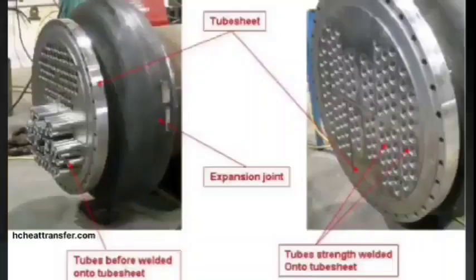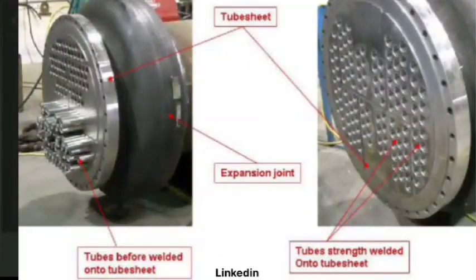And this strength comes into the picture when it is a fixed tube sheet. When it is a U-tube or floating head, it doesn't matter, because no load will come; the tube is free to expand, so there is no differential thermal expansion. In the fixed case, it is attached to the shell, so this picture comes.